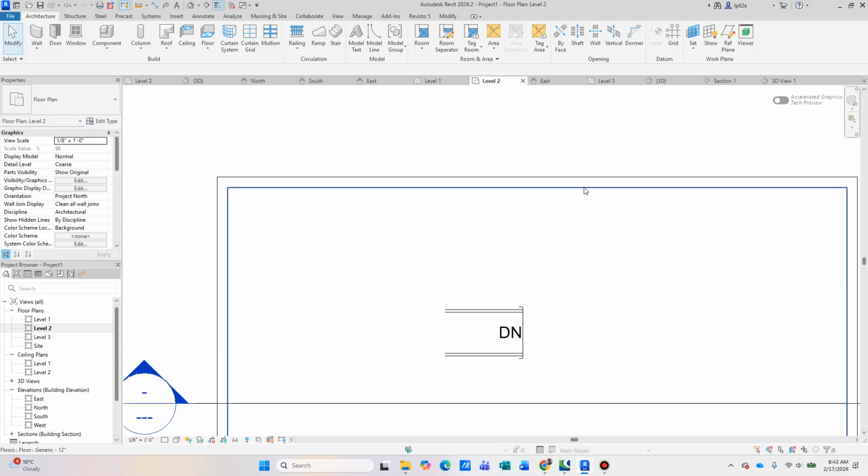You probably need to press the tab key several times. If you click on the edge of the floor slab, you will cycle through the selections or items that are overlapping like this. As you press the tab key, the description will change as well.